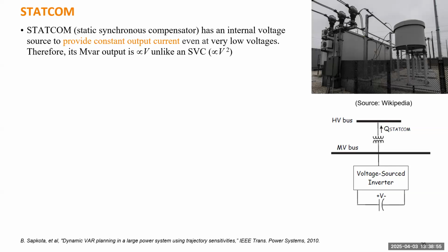When you connect renewable energy to the grid through a power electronics inverter, inverter-based resources have been there for a long time, but these are not for generating any power. It just tries to provide reactive power. Which also means you can easily make inverter-based resources for solar or wind energy behave like a STATCOM. They can easily operate as a STATCOM.